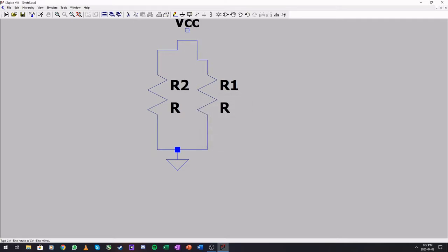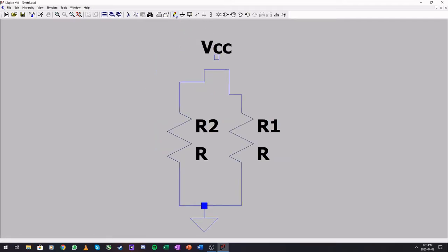You can label something and say this is connected to the power source. You can just label it, label, label, and all the labels with the same name will be connected. So if you have wires traveling all across the schematic, or have different power sources, you can just give them names. This will simplify your life a bit. Okay, next one, resistors,